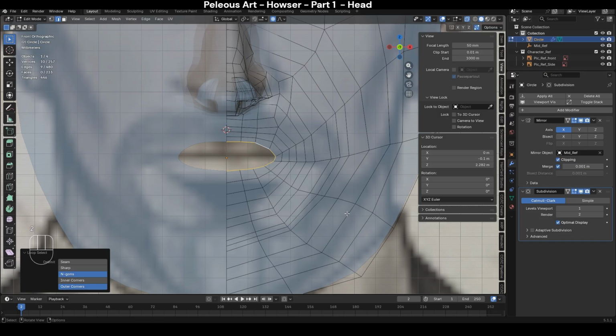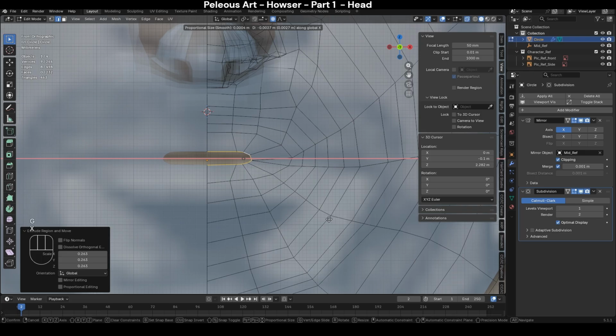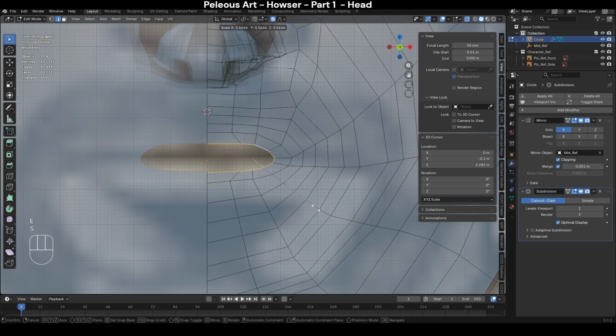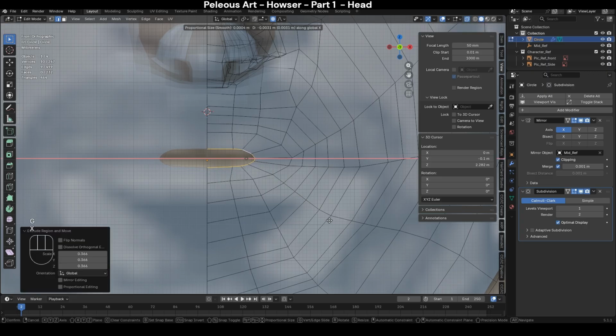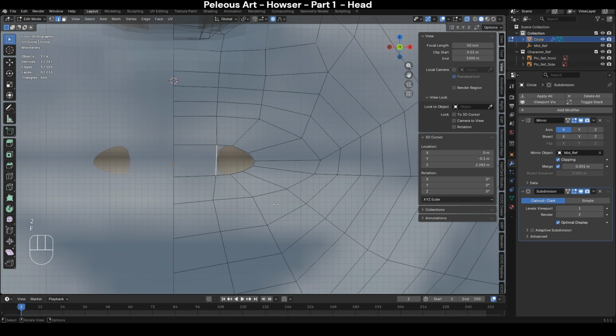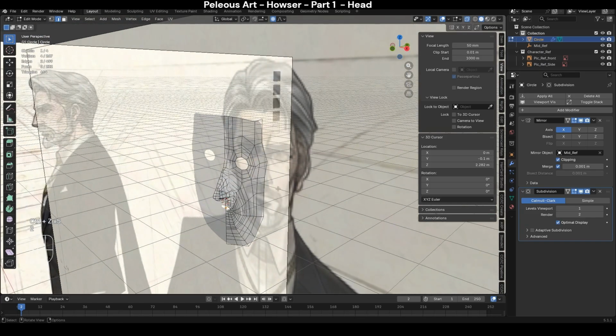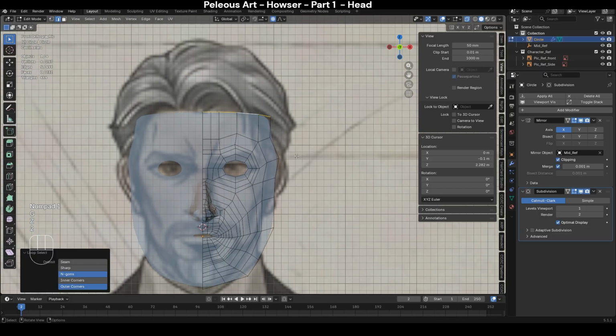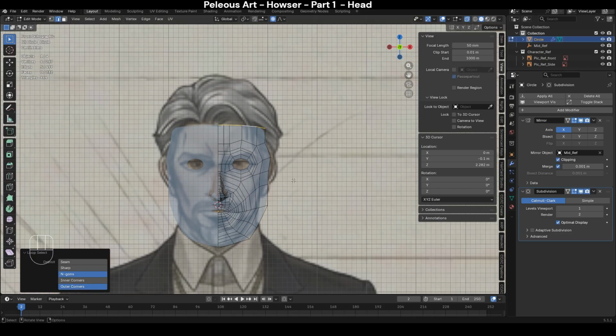The lips, we can add here 2 loops. Let's extrude this, push it to the center without the merge. Otherwise, it's gonna merge our vertices, and move it on the X. Okay. Now if we fill, great. This is excellent. I think that now let's just push that down, so we can have head to work with, and we're gonna pull what we're selecting now backward.